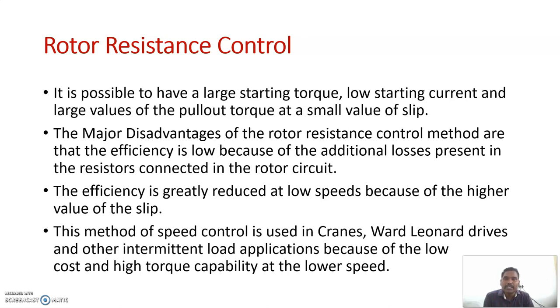The major disadvantage of this method is that the efficiency is low because additional losses are present in the resistor connected in the rotor circuit. Wherever we connect an additional element to the system or circuit, it will definitely reduce the efficiency of the entire system.